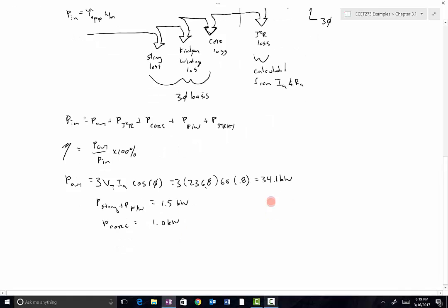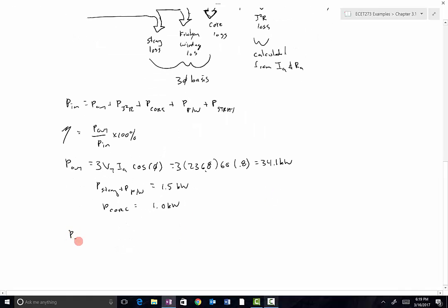The total copper loss, P I squared R, is equal to the magnitude of the armature current squared times the armature resistance, multiplied by 3 because it happens in all three phases of the generator. So it's 3 times 60 squared times 0, because we assumed an ideal generator. In this instance, there's 0 watts of copper loss.